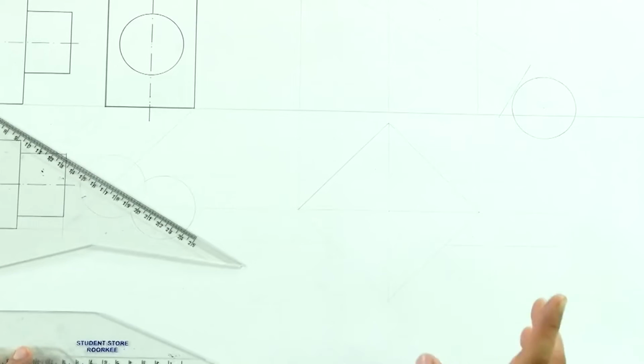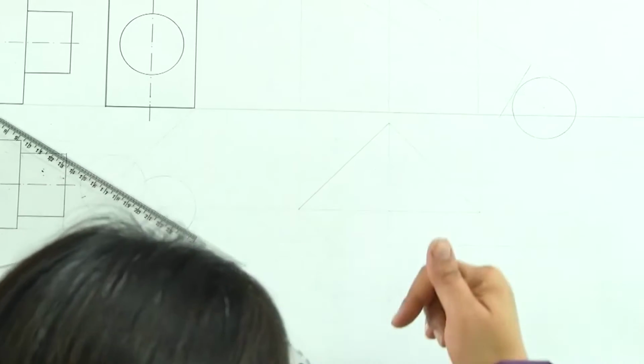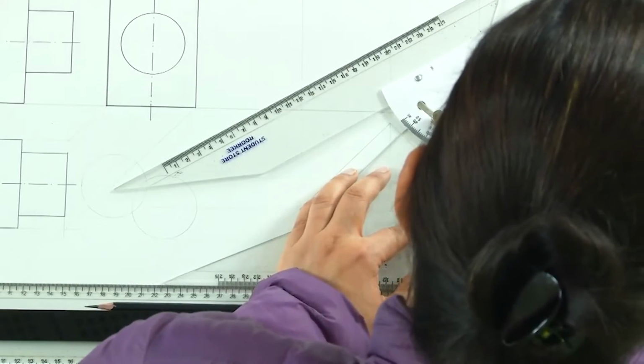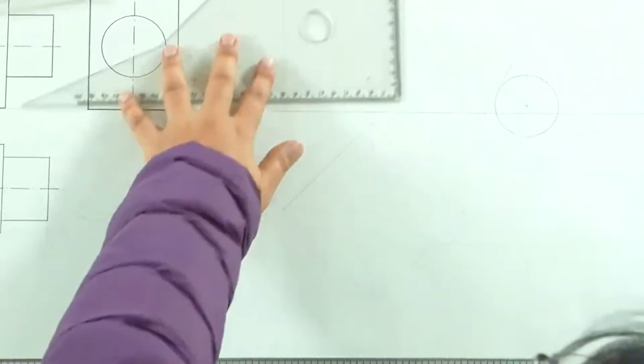So, we will again get back. We can have the same 12 divisions for the same circle. We can use those divisions to get it back onto the HP. So, we will draw these divisions here first. This is one of the most trusted ways of projecting your circles.